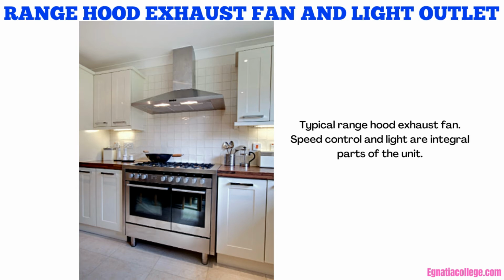An exhaust fan simultaneously removes odors and moisture from the air and exhausts heated air. The electrician, builder, and/or architect may make suggestions to guide the owner in making the choice of type of fan to install. For the residence in the blueprints that accompany this book, a separate wall switch is not required because the fan speed switch, light, and light switch are integral parts of the fan.